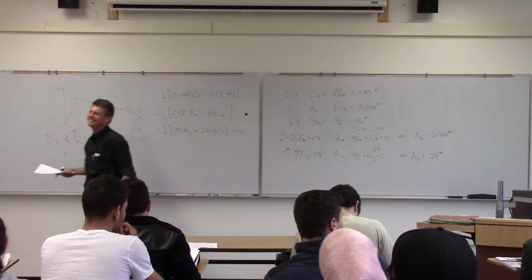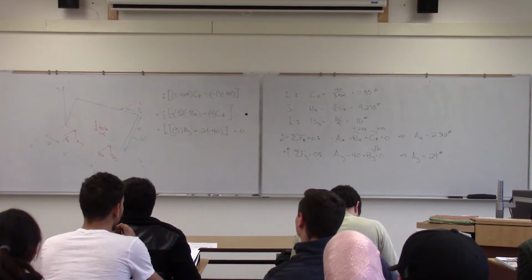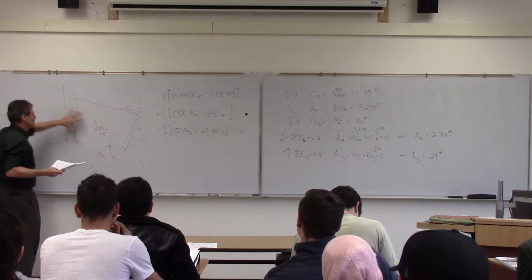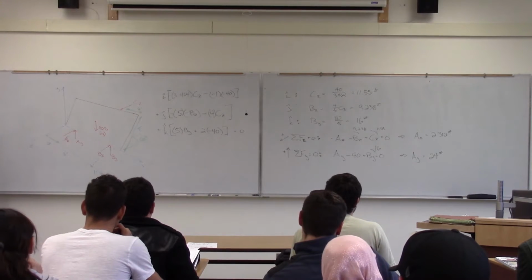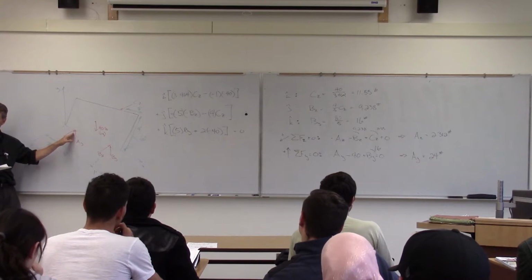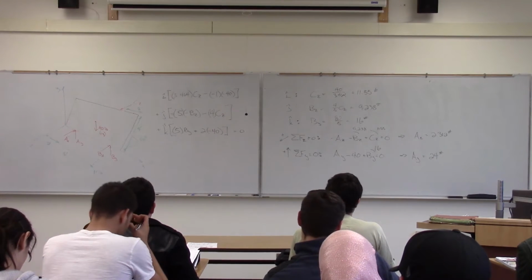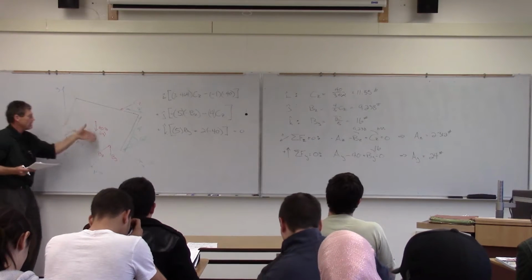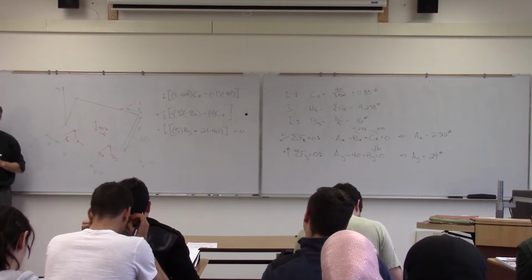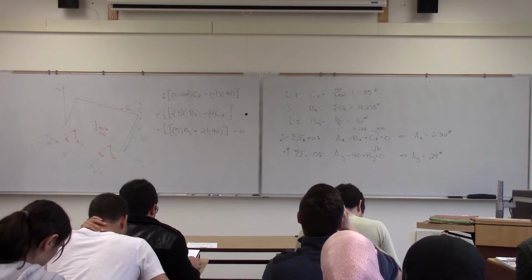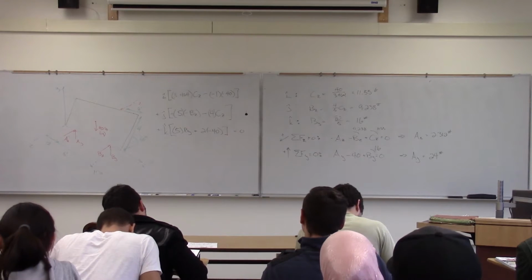Question? Are we assuming that the x's are equal to 0? Yes. Now that's a good point. We talked about that earlier. When we think about it, it's really unstable, because unless I said these had friction or anything like that, I really don't have anything to resist in the x direction. But notice the only force I have is a vertical force, and this support force is perpendicular to that in the z direction. So yes, x is automatically equal to 0 in this particular load situation.